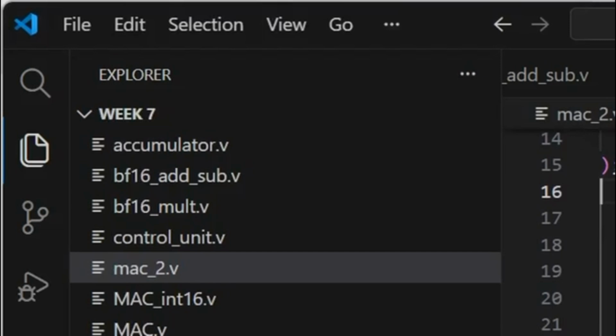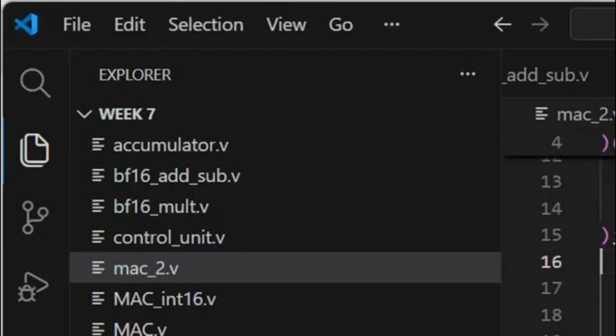It takes a 16-bit and a 31-bit input. Just multiply that and keep it aside. Then as an array of inputs comes in, every multiplication gets added at the end, and that's our final product, which is more of a dot product, as I said, for an accelerator.